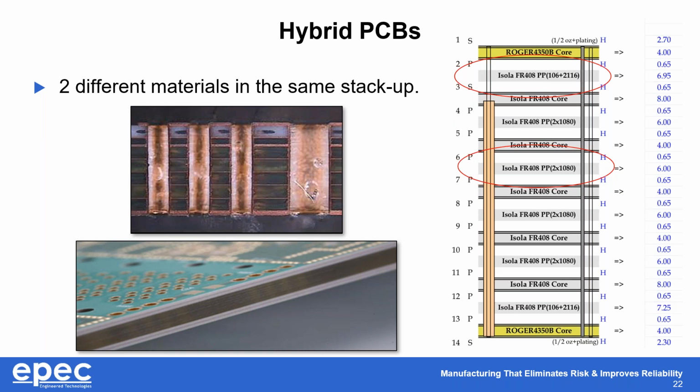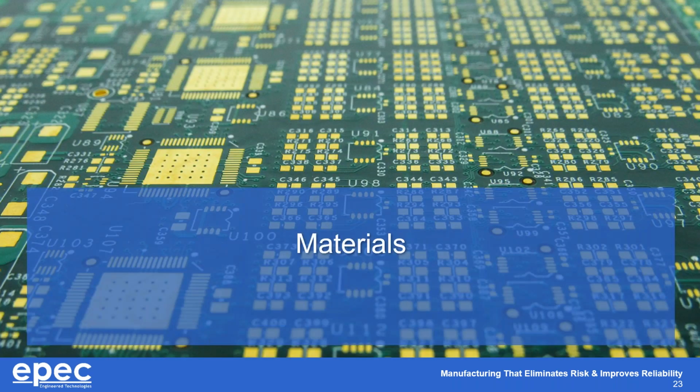So for us, we like to work with our customers from the very beginning. They give us the stack up they're trying to do. We give them what the most cost-effective stack up would look like, and then they can go through and build off the rest of their part. Because again, it also is about cost, right? There's probably 10 different ways to stack this up, and it's all around what do I have in-house, what's the most common pre-preg, and as a manufacturer, I can help you with that. I can't help you identify what you need for your application, but I can certainly help you get cost out of this design by telling you the most common and most cost-effective ways to stack it up.